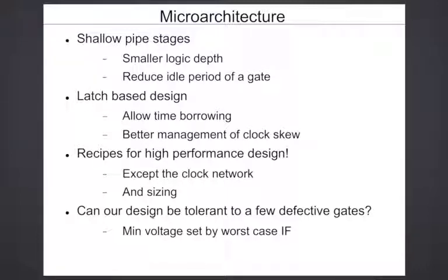In addition, during operation, you can have errors in the memory due to soft errors, right? An alpha particle hit or some small perturbation will flip the cell. Error control coding is done so that if you have one bit failure, you can correct it. So you have SECDED, single error correction, double error detection. You can have double error correction, triple error detection. You can have various complexity of codes depending on how robust you want it. Seamlessly for the designer, you don't even notice it. When you assume there's a memory, the coding takes care of it. You assume the data is correct, and you can make that assumption with very high confidence, with very high probability, it will be okay.